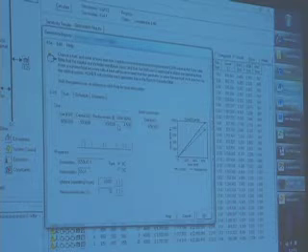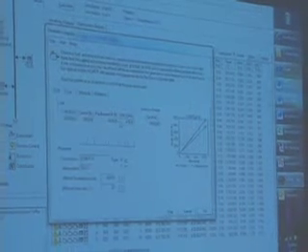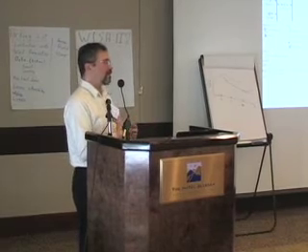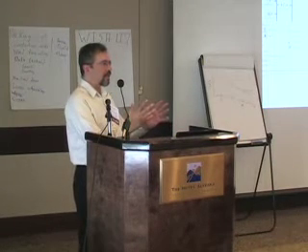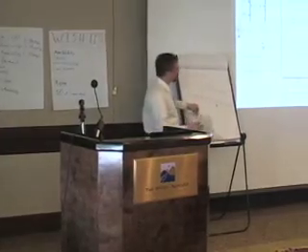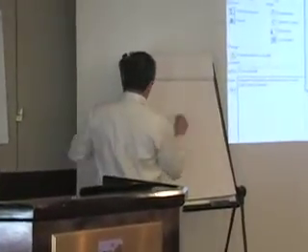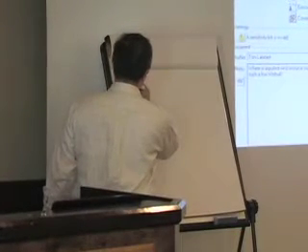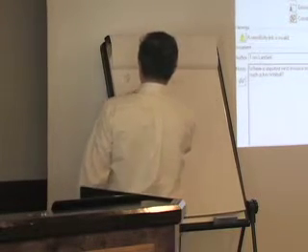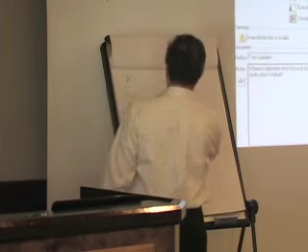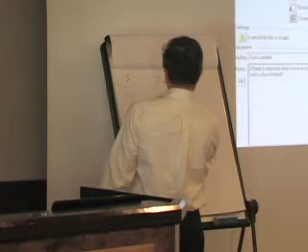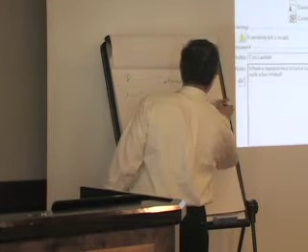So when you see something like the maintenance cost for diesel is 3 cents a kilowatt hour, let's say, well, there's implied within that some capacity factor because, just to take an overly simple example, if you have to spend $300 every 10,000 hours, that's equal to 3 cents an operating hour, right?